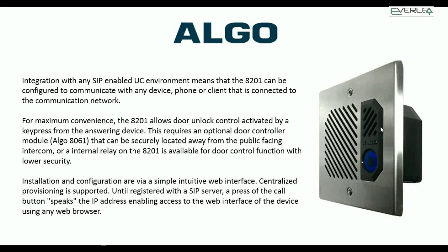The other neat thing about this is it's very simple for a technician to install. Once it's plugged in to the network, the process is you literally plug it in, it powers up. After about 30 seconds it'll give an audible beep, indicating I am ready, I'm working. And if you press the call button, if it's not registered, e.g. you haven't set up auto provisioning or anything like that on it, it's going to tell you what the IP address is that it's sitting on.